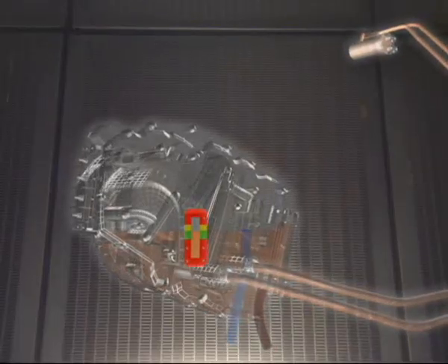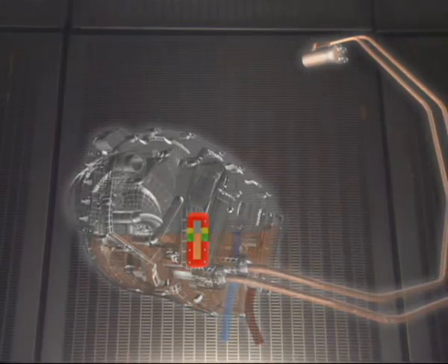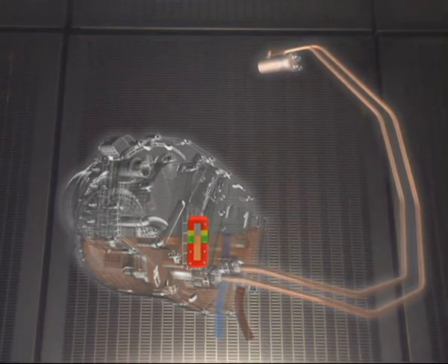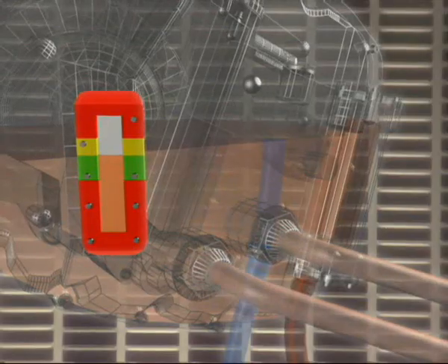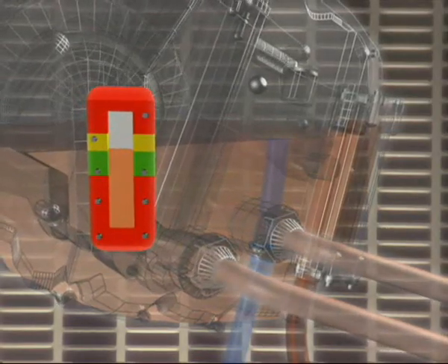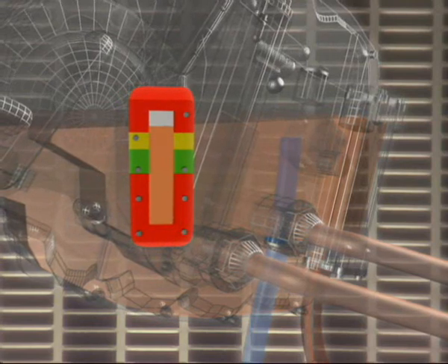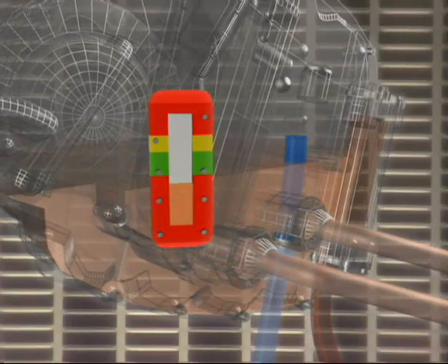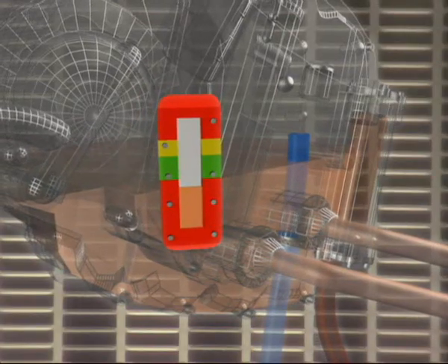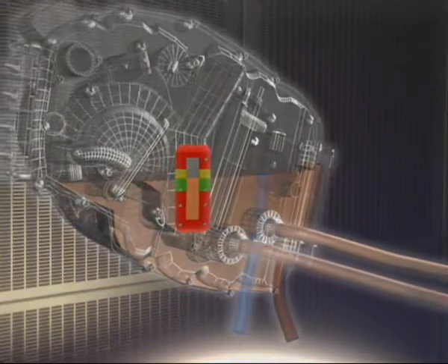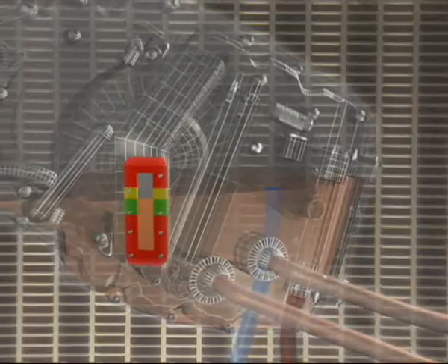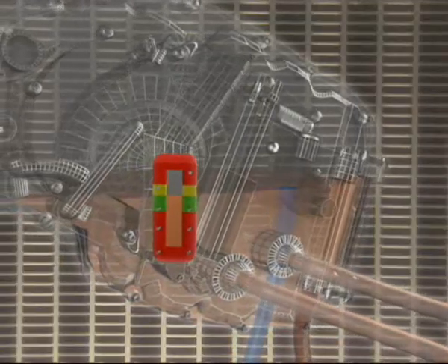The servicing procedure is aimed at filling all the cavities of the circuit with oil, expelling air pockets, and thus setting the optimum oil level. If there is too much oil in the IDG, the operating temperature increases, and there is a risk of IDG disconnection in flight. A low quantity of oil may be at the origin of a low oil pressure and electrical frequency fluctuations. The generator may be lost in flight. After correct servicing, the optimum oil level is at or near the top of the green band.